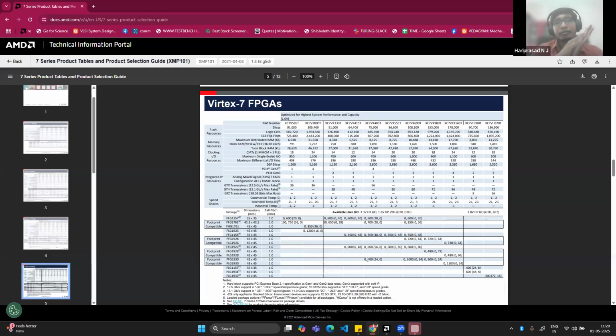And in some cases, we will take the temperature completely to 113, 114 degrees Celsius and power it on there. Okay, there will definitely be some variation, so we will give that buffer. Whenever the temperature goes to 115, 116 degrees Celsius, your clock will be slightly drifting. Let's say 100 megahertz will start showing 100.1 megahertz or 99.99. Your design should still tolerate that kind of variation in temperature and clock. So various scenarios we have to take care of.